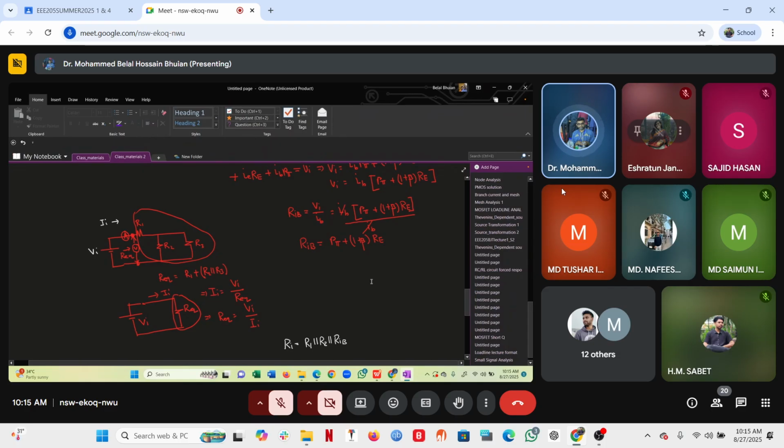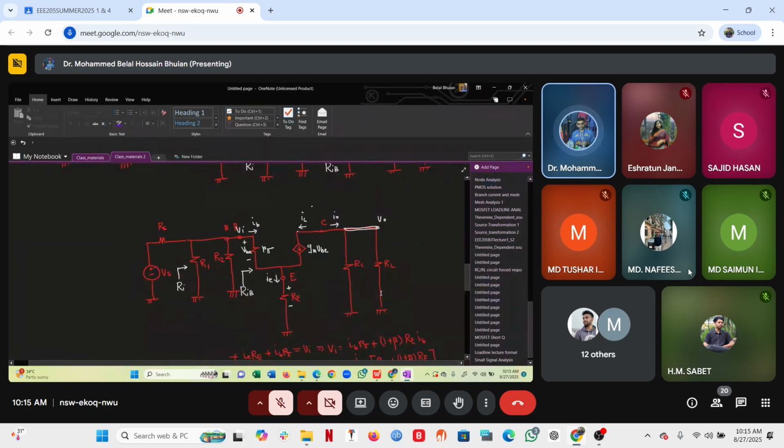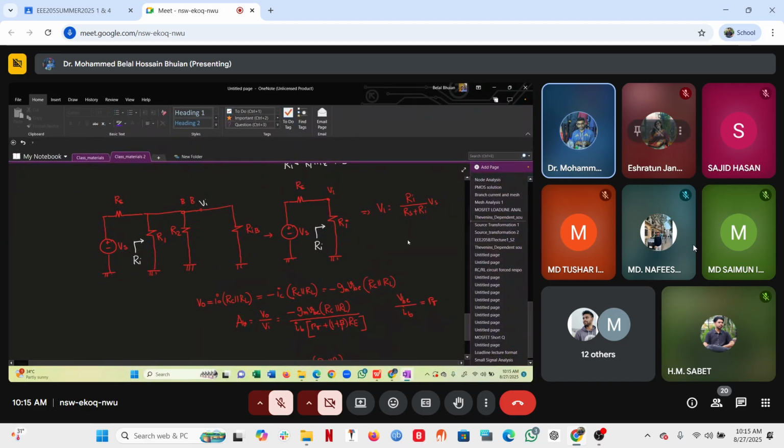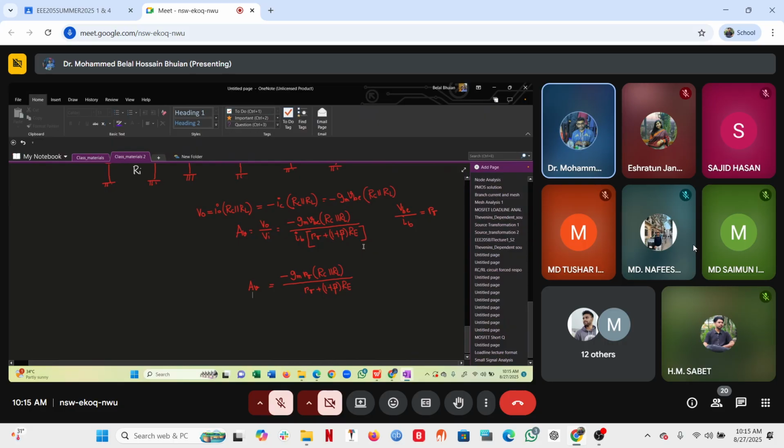So that is the thing that you have to do. In the exams you will have a circuit like that. In that you have to draw the DC equivalent circuit, draw the AC equivalent circuit, replace the BJT with the model, and then do all those things. You have to find the expressions for VI, V naught, RI, all those expressions. So that is a full question. If you can do it right, it carries a lot.